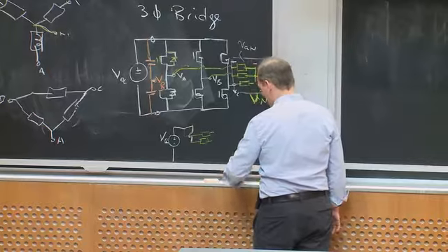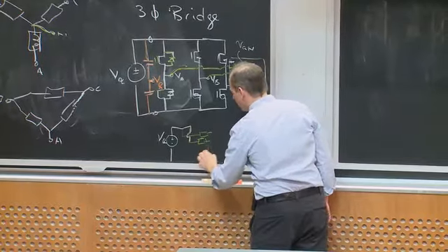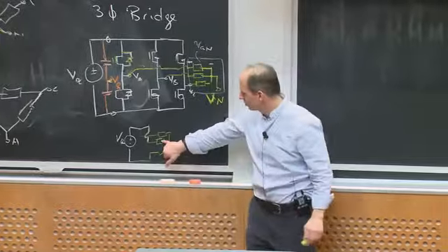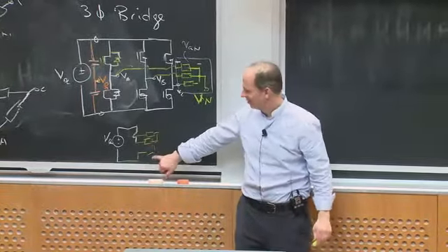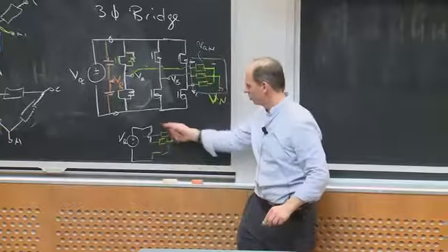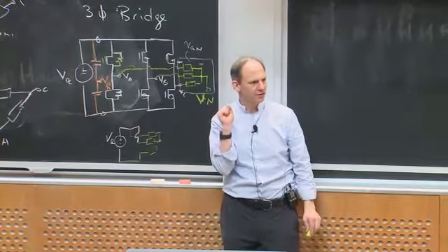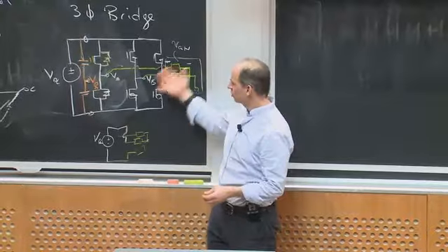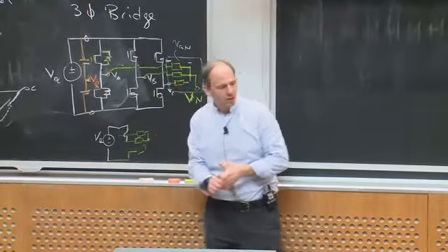And if the last guy has the bottom switch on, I tie him to the bottom, right? So if I have 2 to the top and 1 to the bottom, this node voltage, if these green boxes are all equal impedances, will be 2/3 of the way to the top by voltage division. Does that make sense? Okay, so that's the way you tend to think about it.